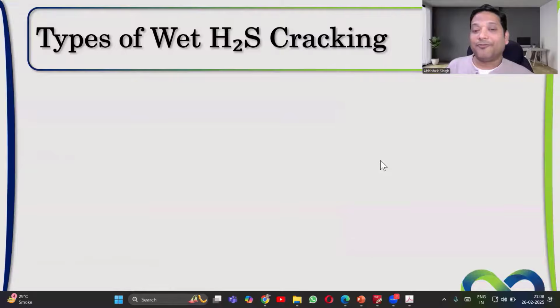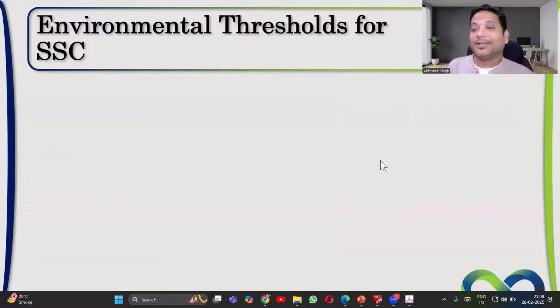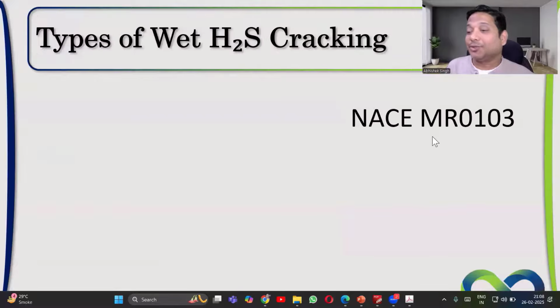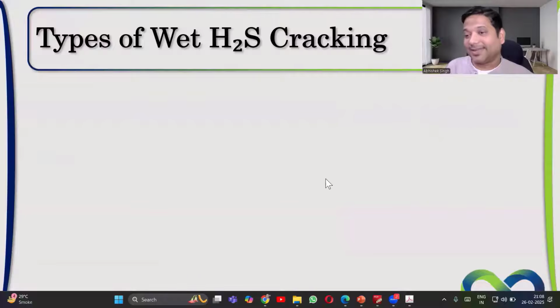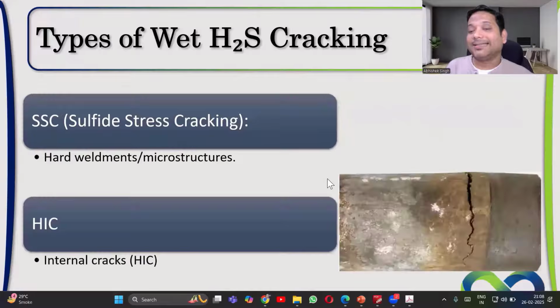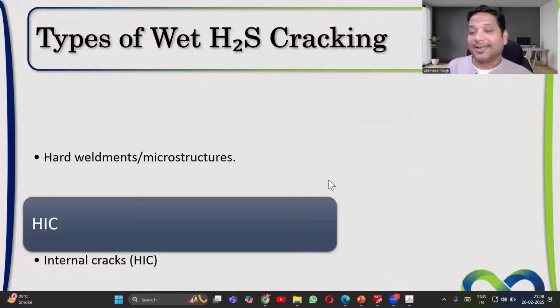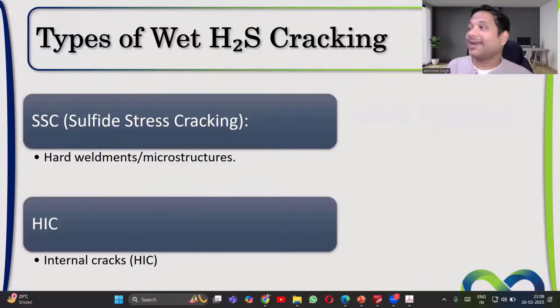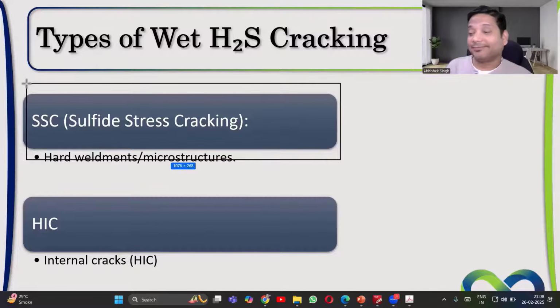So moving forward. When we talk about NACE 0103, NACE 0103 only talks about SSC. It does not cater to HIC. So when you are applying NACE 0103, it is only applicable to SSC.